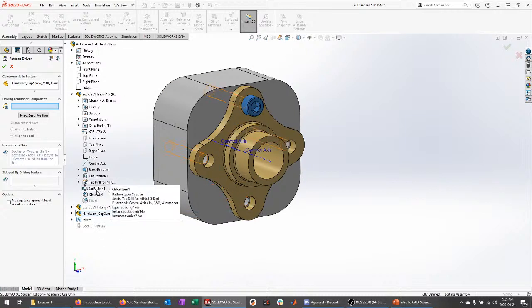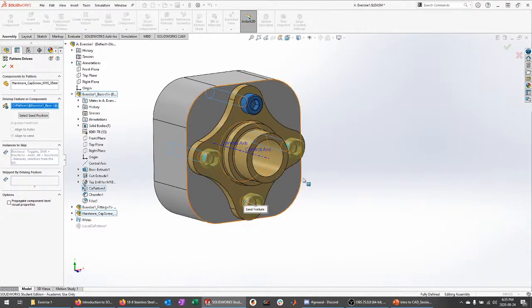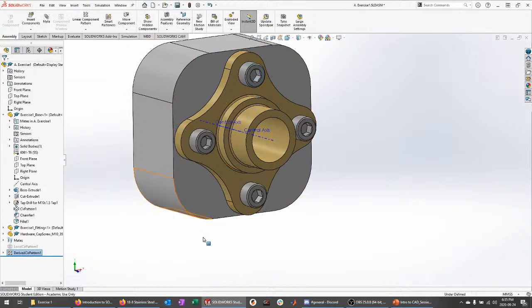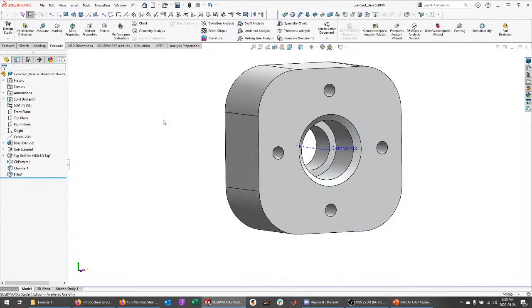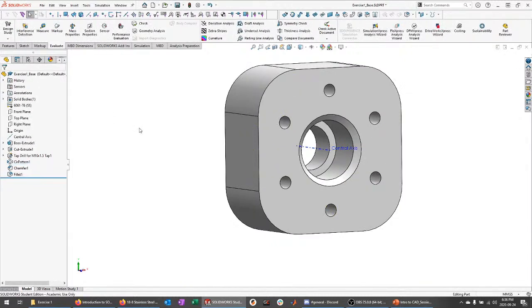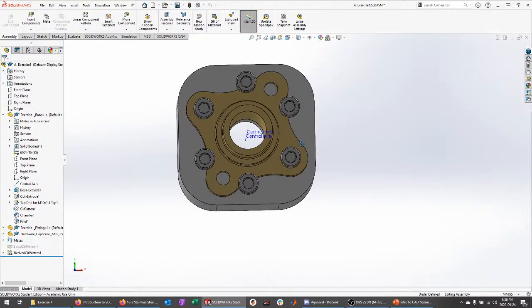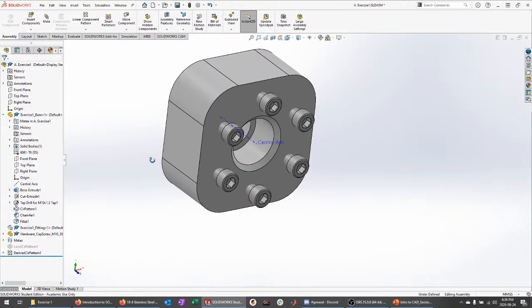So in this case, I'm actually going to select that circular pattern within the base part that I just edited to 6 and then back again. Go ahead and select that. And you can see that'll fill in the other 3 screws. And now, if we were to go to the base, this will be a little bit funky because I didn't actually constrain the screws based on the base. I constrained it based on the flange, which won't update as we do this. But if you wanted to update that to 6 and then go back to the assembly, that'll update the pattern of screws to 6. And again, we don't have the fitting here. That isn't referencing anything, so we'd have to update that separately. But our screws will auto-update.